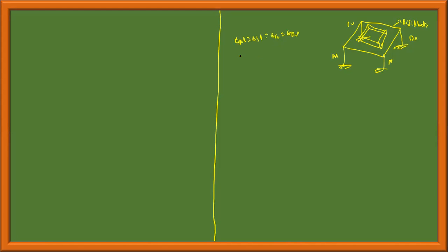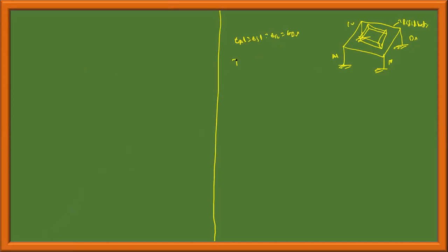But the total load, total force, is equal to the sum of the forces in aluminum plus steel plus copper plus brass. Load is shared. What ratio, we don't know, but the summation of the loads shared by each and every column is equal to the total load. This is a parallel combination. We have discussed that.